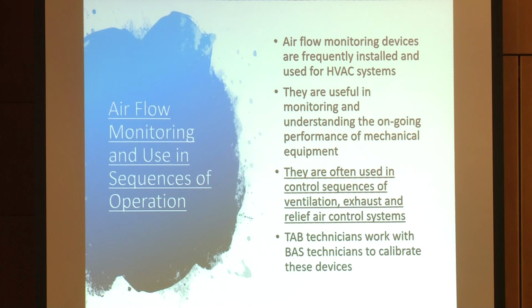That standard has grown in importance through the years, and now it's gotten to a point where we're actually doing demand control ventilation. So now we're operating the ventilation at different levels for different levels of carbon dioxide in the space. And so understanding how that works and making sure the airflow monitors work is very key to the TAB process.